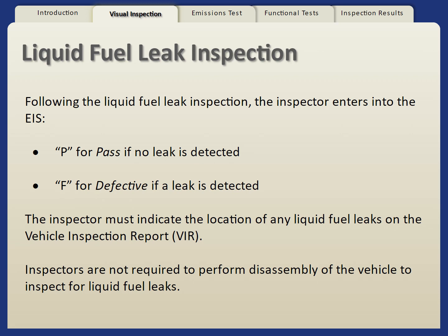The inspector must indicate on the vehicle inspection report the location of any liquid fuel leak. Inspectors are not required to perform disassembly of the vehicle to inspect for liquid fuel leaks. No special tools or equipment other than a flashlight and mirror are required.